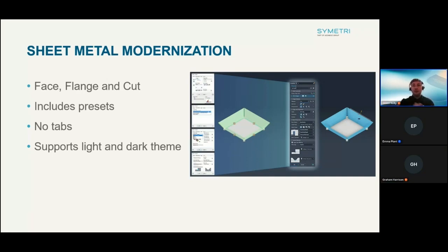One of the main reasons that I'm pointing this one out is it can now include presets. So this is included for the face command, the flange, and the cut options. If you're not aware, presets allow you to configure the dialog box and have it as a standard within your company or within your individual machines, depending on where it's pointing to in your project settings.